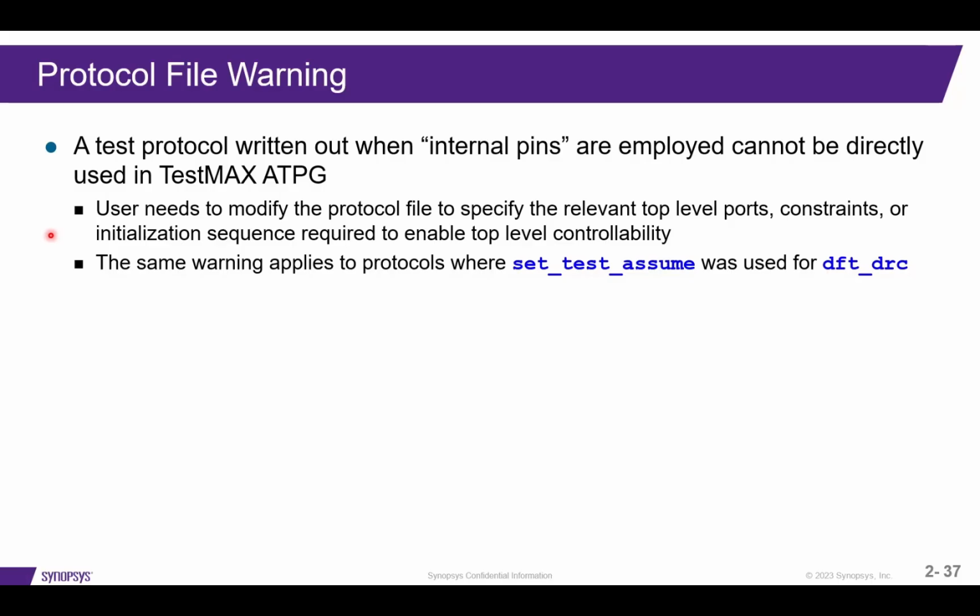So think of running TestMax ATPG as applying signals at the chip package. You have no access to internal nodes of a design. You will have to write the proper initialization sequence applied from the package pins in order to initialize your design. The same warning would apply to protocols where the set test assume command was used for DFT-DRC.